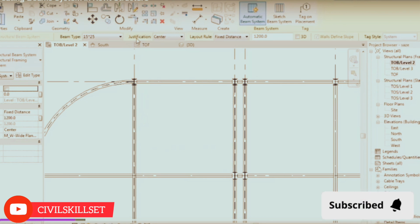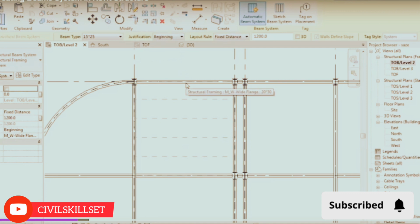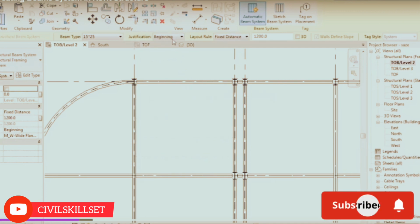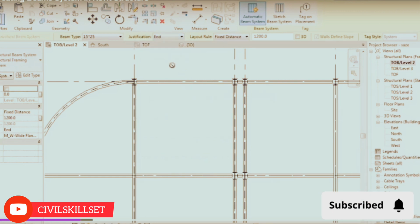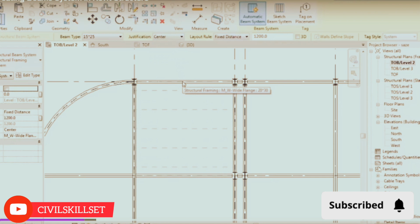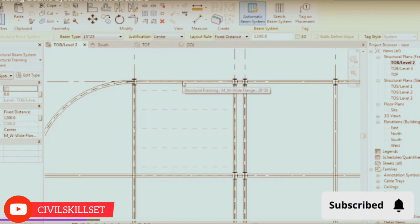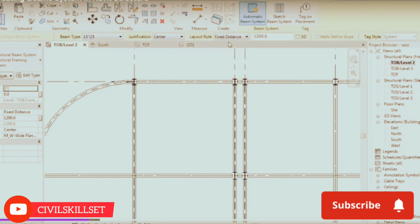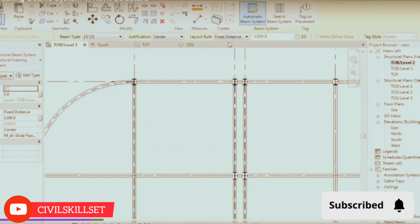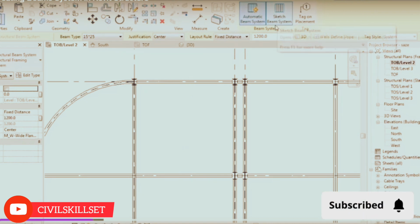Justification was the same thing in curtain walls. If it were beginning, it would start from the beginning and the extra part would be at the end. If it were at the end, it would start from the end and the extra would be in the beginning, and central it would be on the sides. And it's usually used as center. So after choosing the beam type, you're gonna have to choose and select these options too.